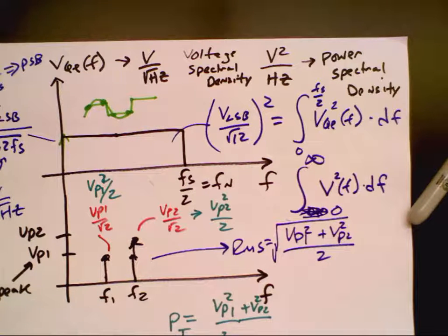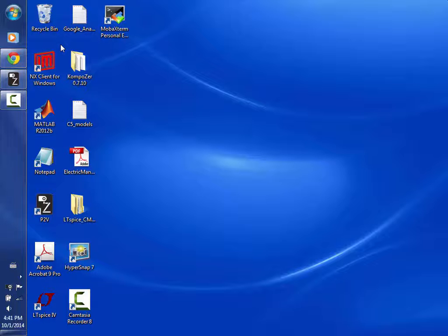Is that the reason why they want you to use coherent frequencies when doing effective bits testing? If you use a coherent frequency, you can get well-defined tones. If you get well-defined tones and you have enough of them, hopefully this will make sense: when you do the FFT, you have a window. So when you window the FFT, if you use tones and they're discrete, you don't have bleeding of your bins from one bin to the other. They're isolated, and so then you can get a better estimate. When you have something that's all random and you do the FFT with this particular window, the tones bleed into one another, and then you don't get as good results.